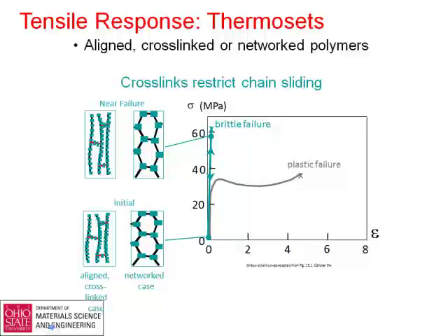Thermosets tend to be less, you can't stretch them generally as far, with the exception of elastomers, and it depends a little bit on how densely cross-linked they are. And the density of cross-linking is something that can be controlled chemically. That controls basically the stiffness and hardness, or durometer, as people like to call it in the plastics business, of the plastics.